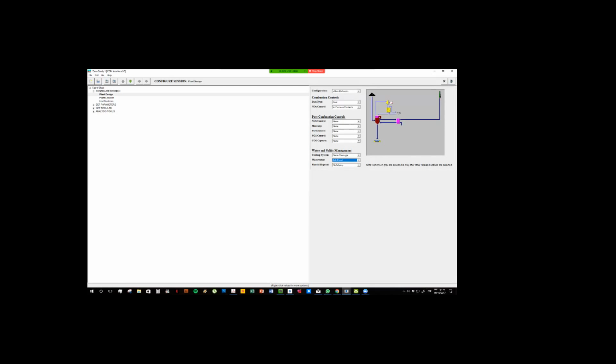In this case, it's treated just as an ash pond. In that case, we only throw it into a pond, and in that one, we wait for it to sediment and so on to use it again as gray water. But we can have a more sophisticated treatment, for example, a chemical treatment or a mechanical treatment. In those cases, it's more or less like the treatment plant that we have at IECM, right? If you have seen that one, it's more or less like that one. It has mechanical treatment, filters and sedimentation, and chemical treatment to treat biological waste and so on.